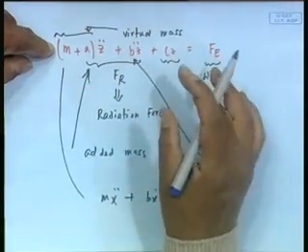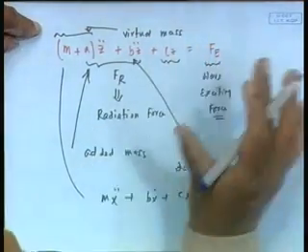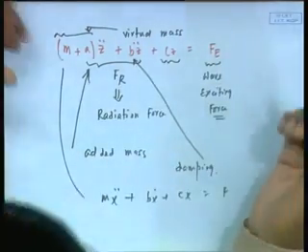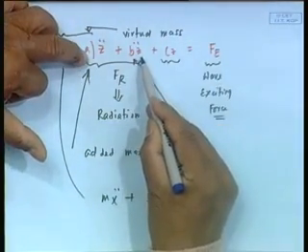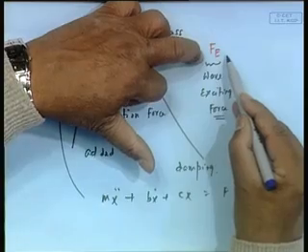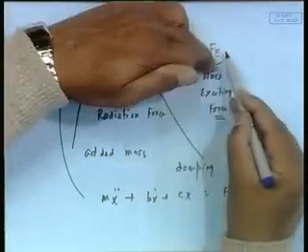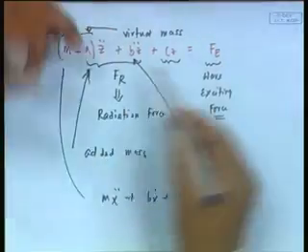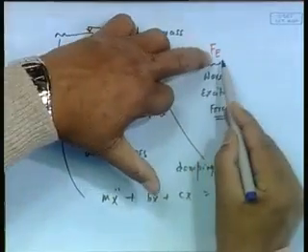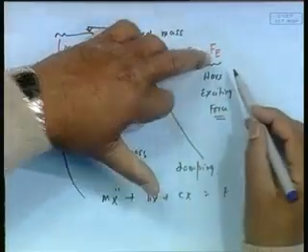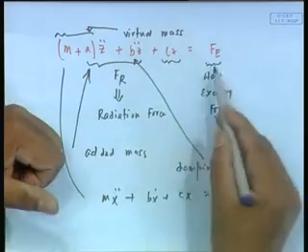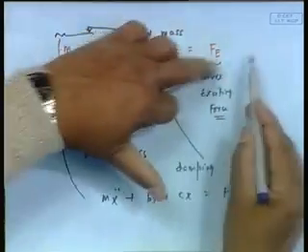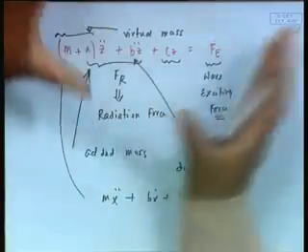Cz coming from hydrostatic depends only on the geometry of the hull, rho g, etc. Where is the hydrodynamics? It is here, the radiation force, and here, the diffraction force. These are the parts where hydrodynamics comes in. Further break it down: added mass, damping. If you break this one down, it will be diffraction force, and one can show they are connected. So this is where the hydrodynamics comes in.